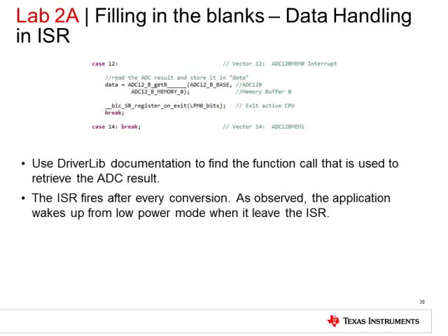The interrupt service routine is already pre-populated in the source code. Enabling the IE ensures that the interrupt flag is set and the code execution vectors to the interrupt service routine. You can set up a function to read the converted result from the ADC inside the ISR as shown.